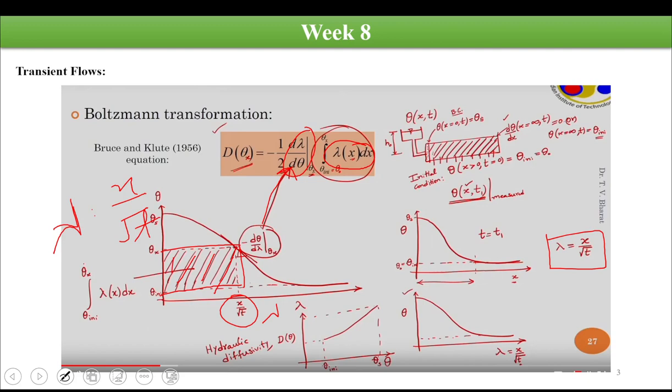And so these are the concepts we have studied for the horizontal flow problem. We have several boundary conditions. We have several initial conditions. That at this point, theta is always at saturation, right? And this point is really far, like that. So at this point, d theta upon dx is going to be zero. And we can also say that at any x greater than zero and t equal to zero, theta initial is theta naught at that point.